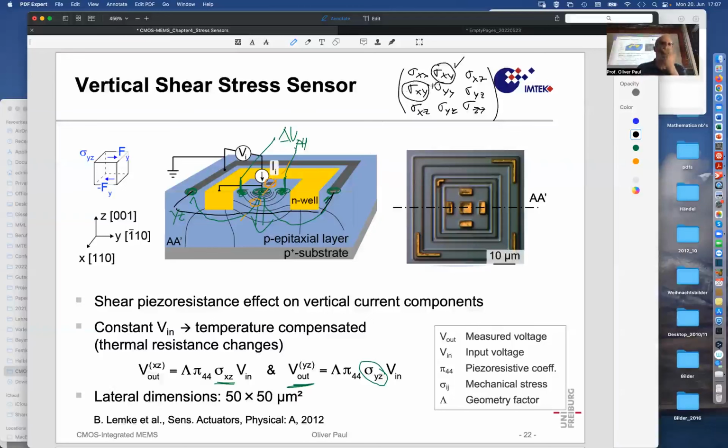So they are kind of done. They can be done by in-plane piezoresistive bridges. Then what we also can do actually is measure the difference of those, sigma xx minus sigma yy. That's also okay. So of those 3 components, we can actually measure 2 combinations, one pure and one in combination.